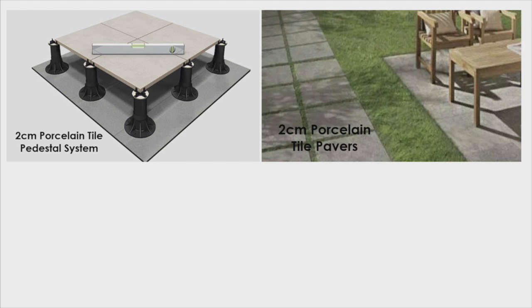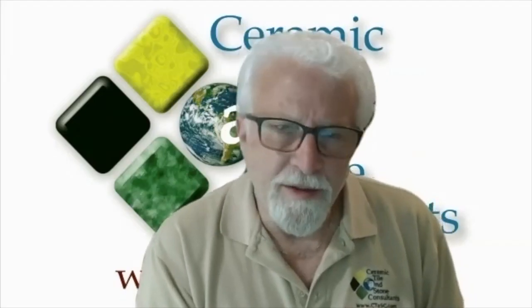Another way they're promoting this product is for landscaping pavers. Now, these can be installed over a sand bed or even directly on the ground in some cases, if it's done correctly. Sand bed installations have been around for a while, but you've got to have a drainage plane. You've got to compact the sand.